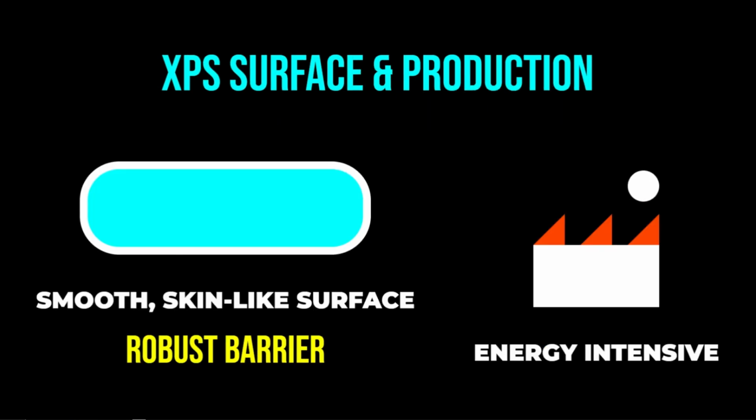XPS typically exhibits higher compressive strength than standard EPS, making it the primary choice for inverted roofs and perimeter insulation where the material is in direct contact with soil and groundwater. Its smooth, skin-like surface and high density provide a robust barrier against mechanical loads. However, the manufacturing process is more energy-intensive, and the choice of blowing agents historically impacted its environmental footprint compared to